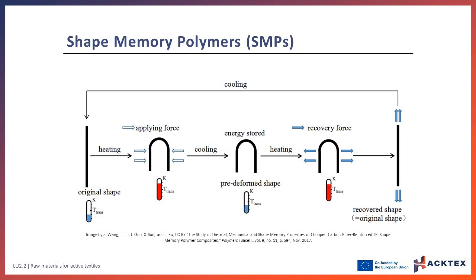On the other hand, shape memory in polymers is not an intrinsic property, so it requires the programming of a temporary deformed shape. Their most common trigger is also temperature, although there are shape memory polymers that react to light. In this case, we talk about two kinds of segments instead of phases.